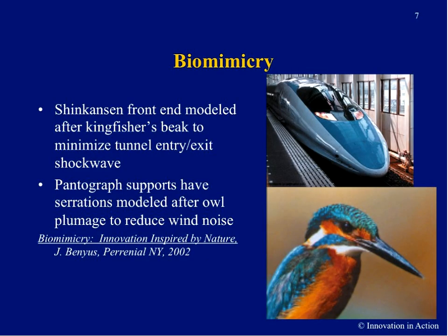One of our favorite tools is biomimicry, the idea of design inspired by nature. The example shown relates to the early development of the Shinkansen, or bullet train, in Japan. When they first started pushing the speeds faster and faster through conventional existing tunnels, they had some problems with shock waves. As you build up a slug of air in front of the train pushing through the tunnel, and you hit the other side and you get a change in the boundary condition, you get almost a sonic boom. It's subsonic, but you get the shock wave effect.